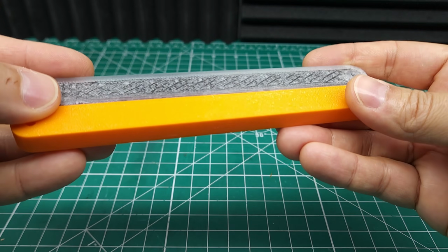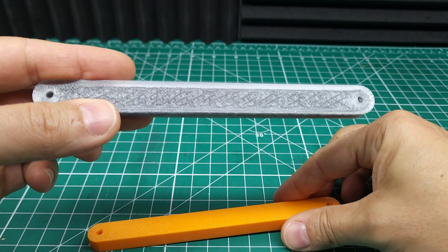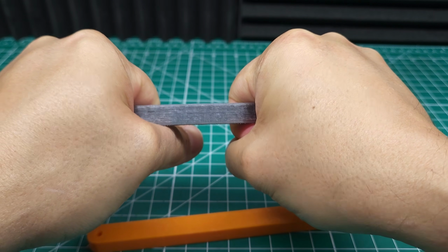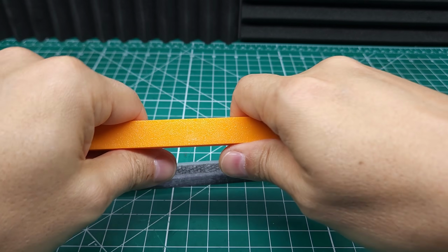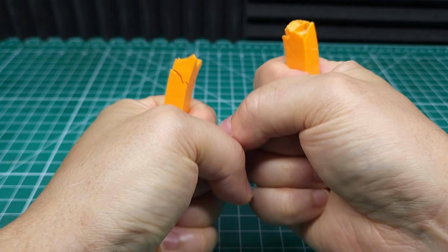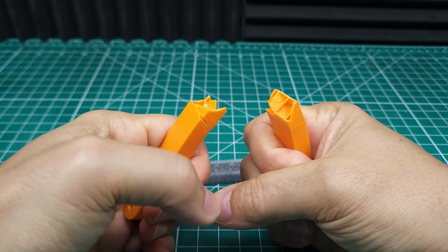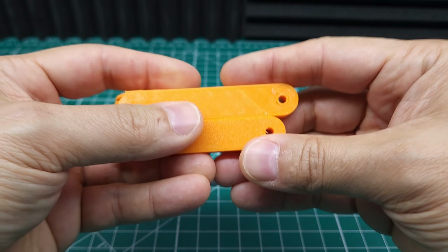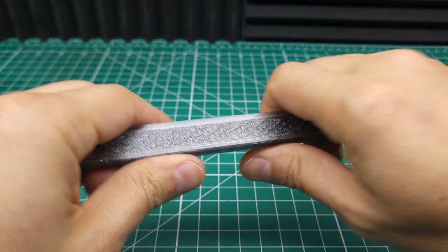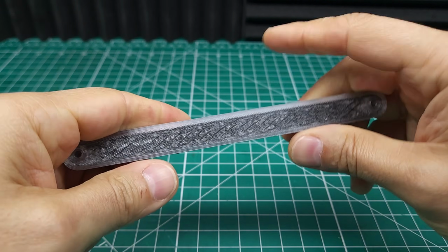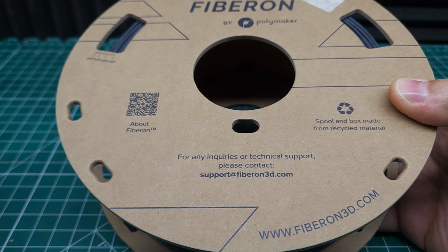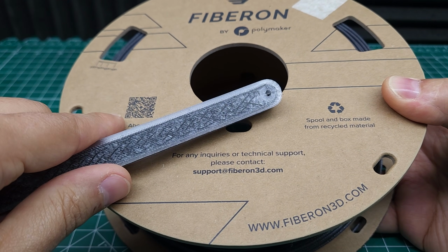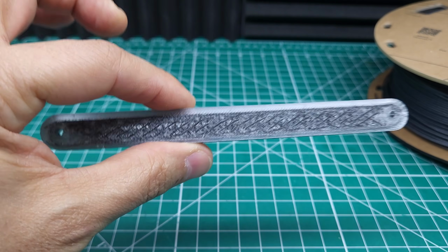And the result is very, very clean, but the difference in material property is dramatic. I can barely flex this at all, no matter how hard I try. However, regular PETG bends and snaps pretty easily. Of course, you could print this stronger with more walls and infill, and PETG really isn't appropriate for this particular part. But again, with that carbon fiber reinforcement, it's a completely different animal. And it's important to remember that we can print parts like this with exotic materials as well and the carbon fiber in them, though I think we're going to save a lot of money doing it like this.